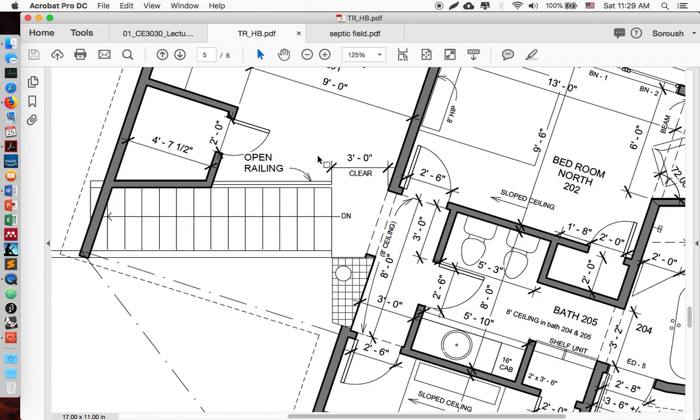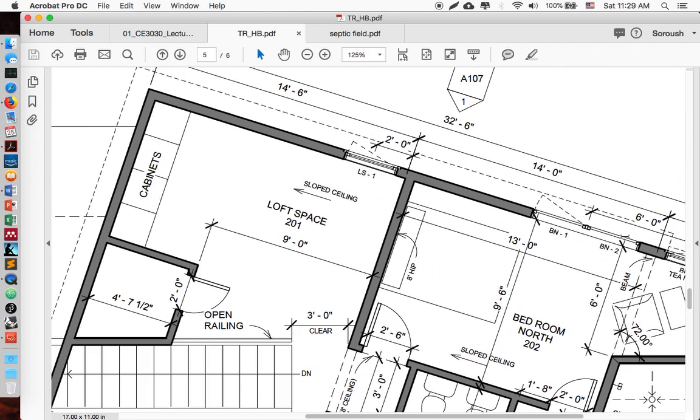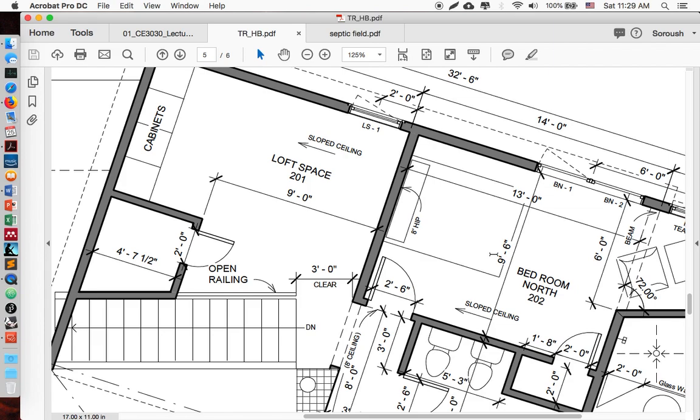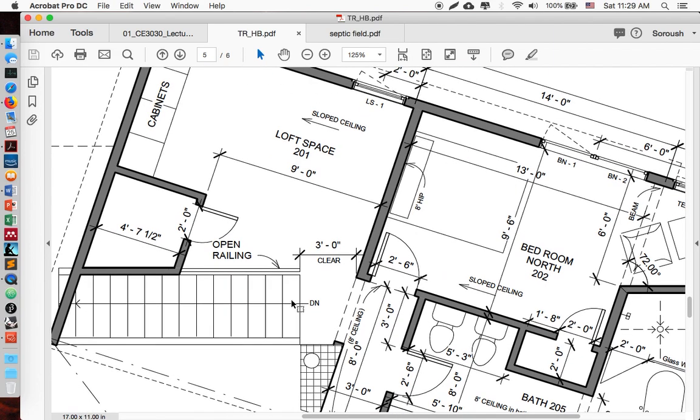So if I cut through somewhere in my drawing and I see a line in front of me that I'm not cutting through, I put it in the second hierarchy format. Then I go with the door system, or if I have a window, I put the window and door in the second hierarchy of the line weight, then text as a third, and dimension as a fourth, and hatch, which we'll get into later in the course, is going to be another level in the line weight.